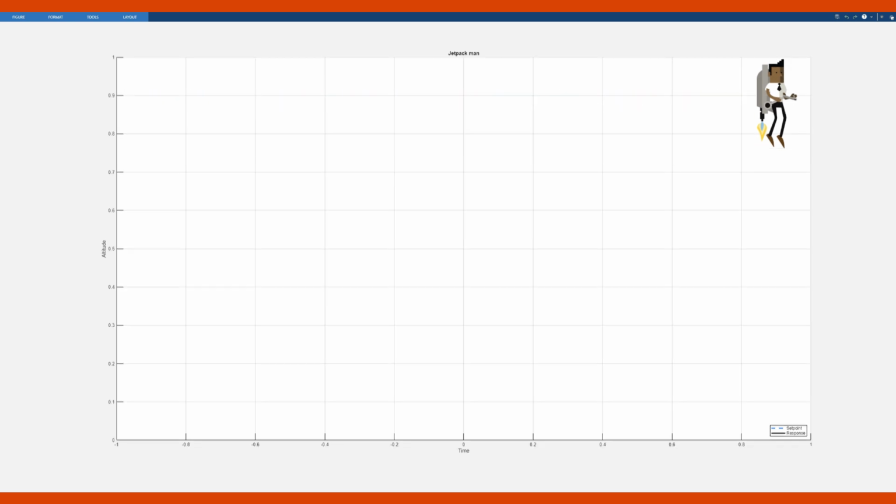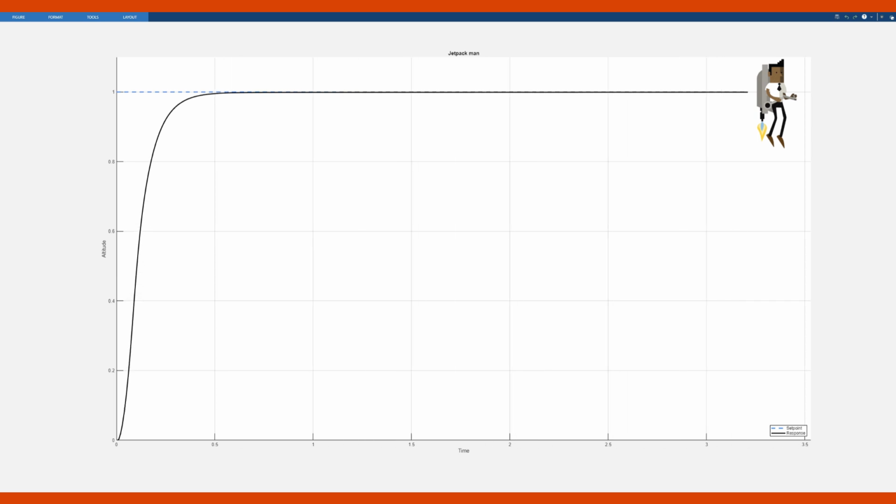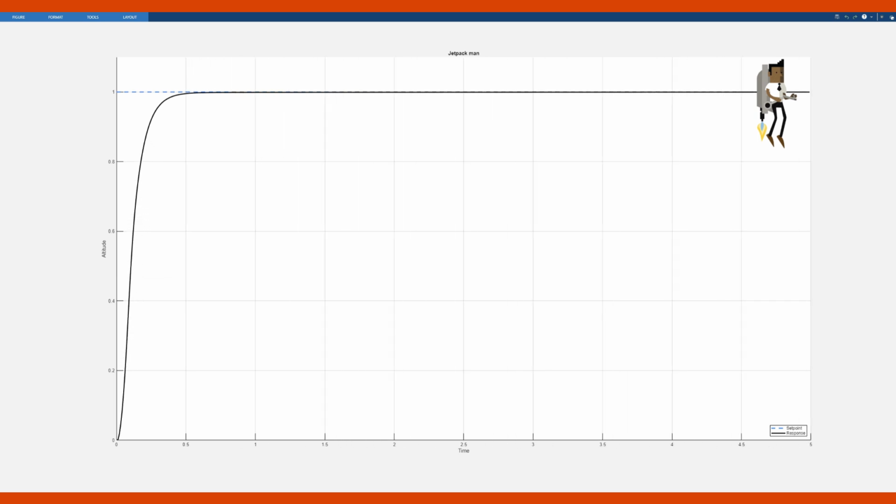We fix this by switching to proportional integral derivative control, or PID. PID control adds a third parameter which helps us to compensate for the external forces acting on Jimmy. Let's see what happens now. Perfect! With the addition of the integral gain, we're able to compensate for gravity and get Jimmy back on target. The system is back to being critically damped, just like we want.